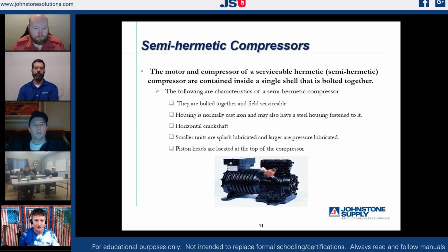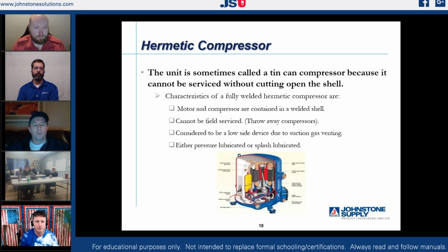If we talk about, hold on, one second. I've got to mention a comment on that real quick. So the efficiency on that compressor, when you think about it versus a scroll, where the scroll plate is rotating in a circle the entire time. You said the compressor efficiency on this is not as good as some of the other ones. Think about that piston. That piston has to move up and back. So 50% of the compression cycle is the compressor going the other direction, where it has to go back to cycle it back up, versus a scroll that is continuously going in one direction.